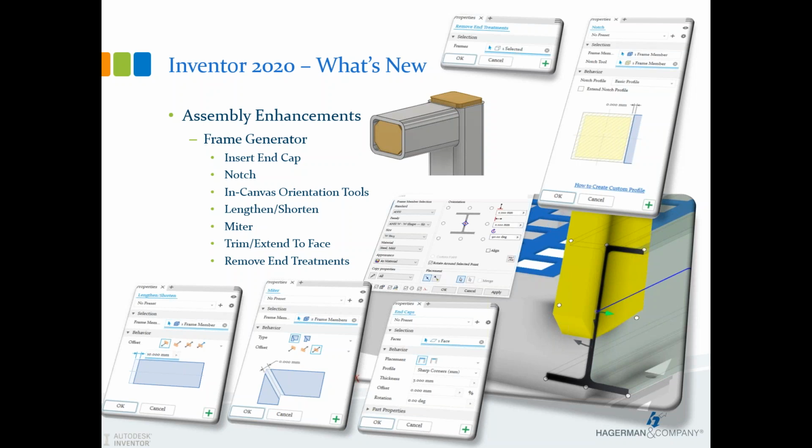We've also got some in-canvas orientation updates as far as orienting the members when we're placing frame generator members. The notch command, the trim, extend to face, the miter command, the remove end treatments, and the lengthen, shorten options have been replaced. The dialog boxes have been replaced with the new UIs. So those are becoming more common across the software as we go. We had those in the modeling environment with the extrude, the revolve, and the sweep command, and now we've got some of these added into the frame generator environment as well.